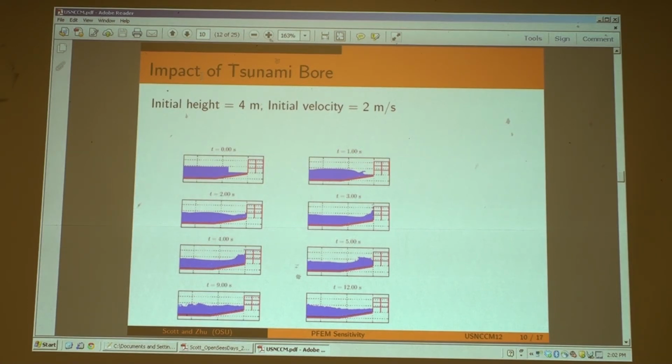And when you iterate, you iterate with a coupled system continuously, you don't go from one to the other. Right. It's a coupled system, but it's doing a predictor-corrector approach, not a staggered scheme. It's monolithic equations where you partition off the velocity equations from the pressure, assume pressure is 0, solve for velocity, then go back and correct pressure. And the non-linearity coming from the fluid, in your experience, is it more difficult to deal with than the one coming from the structure?